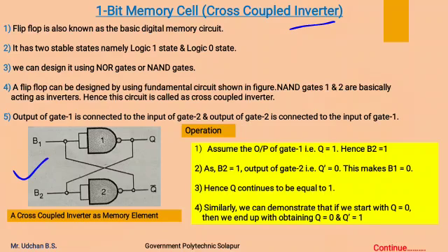In this, a 1-bit memory cell is designed using NAND gates, which includes two NAND gates. Both the NAND gates are going to act as an inverter, as both the input terminals of these NAND gates are shorted together and a common input is given. So with this structure, NAND gates act as an inverter. We already studied this in universal gates.